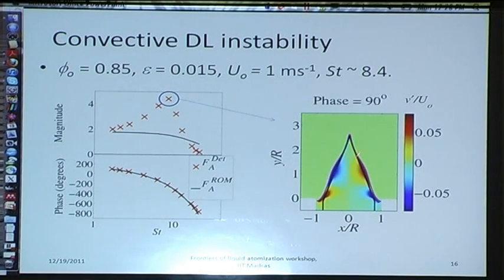You can see that from this movie here, which is plotted for this point, showing what the flame's doing at this point. And the field shows the instantaneous transverse velocity component. And you can see that whenever I get this kind of concave bulge toward reactants, I get an upstream flow acceleration, which is what the DL instability theory tells you, right?